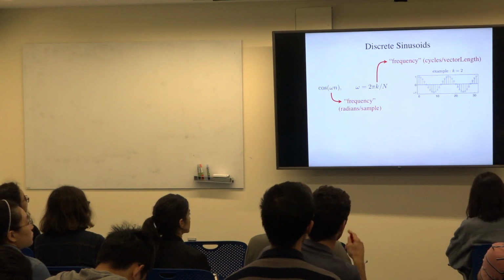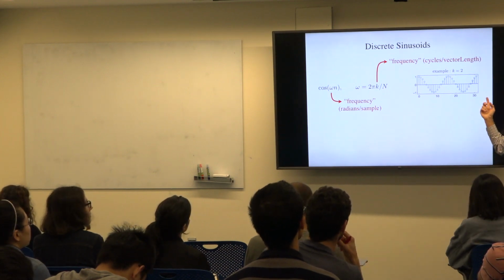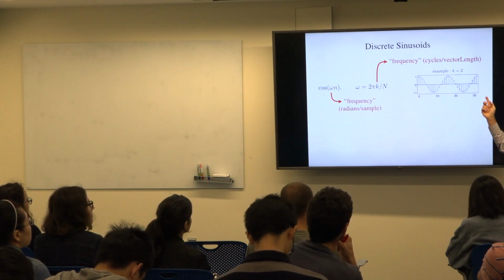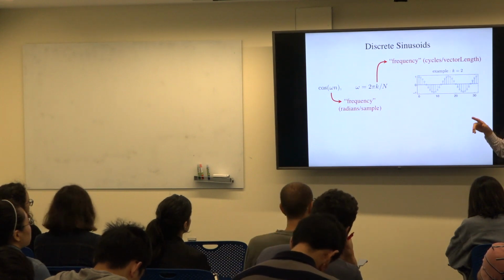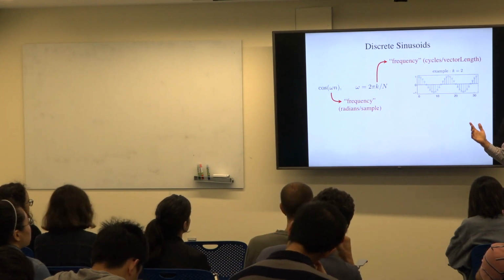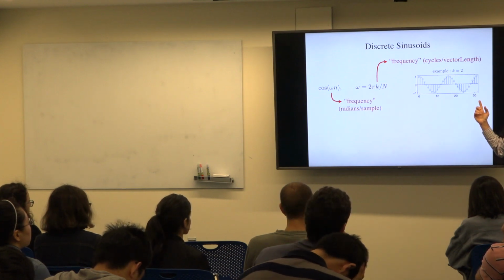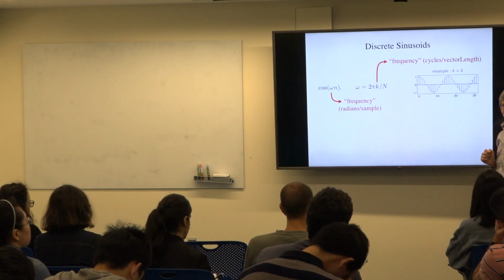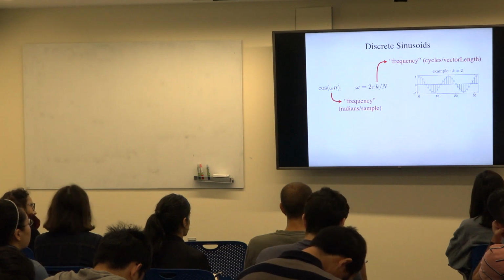Just remind me what the x-axis is. Well, the x-axis is just, I'm going to have some vector that I'm going to put through a linear shift-invariant system, and for now, I'm going to have the input vector be a cosine. And I'm just giving you, here's what I mean by cosine. But the x-axis is also, well, let's imagine that my vector is not just 32 numbers, but it's 32 numbers sampled in time at equal intervals. Okay? All right, so that's your basic cosine.